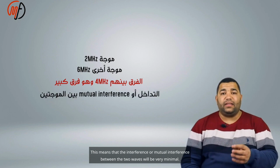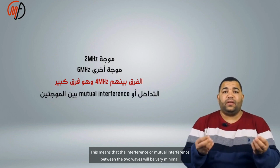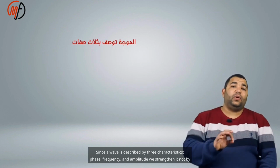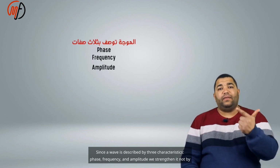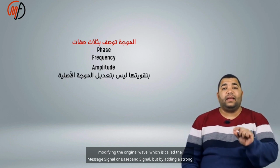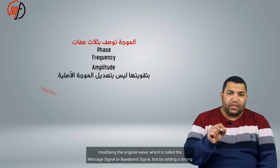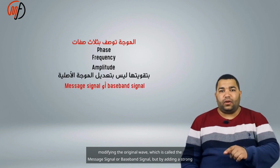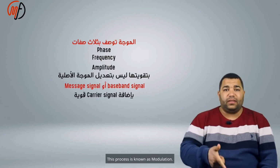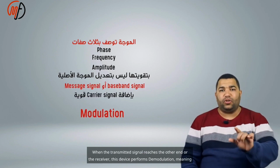This means that the interference or mutual interference between the two waves will be very minimal, since a wave is described by three characteristics: phase, frequency, and amplitude. We strengthen it not by modifying the original wave, which is called the message signal or baseband signal, but by adding a strong carrier signal to it. This process is known as modulation.